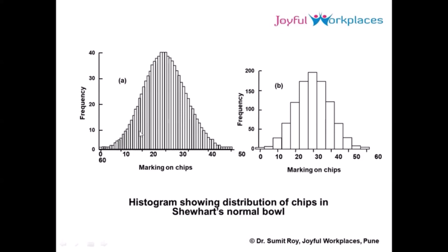Thank you, sir. Okay. What I said just now is through the example of a diameter of a part which is being manufactured through a simple lathe machine. And what I said is that if I continue to manufacture and take the dimension of that particular diameter, and then build up the dimensions by taking more and more samples from the same process over a period of time, we will come to a frequency diagram which will look like this.